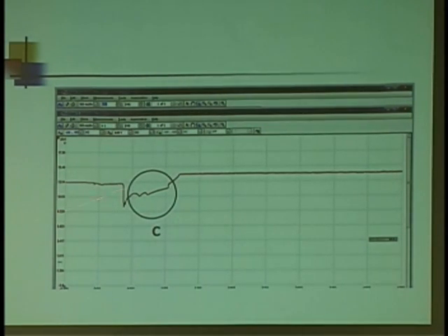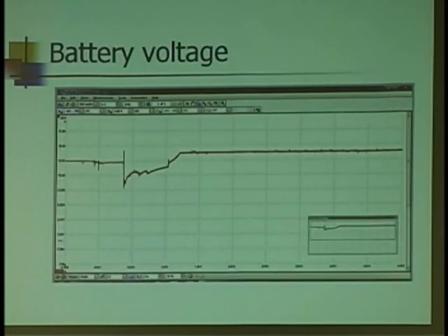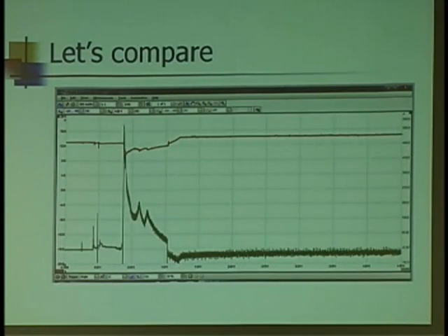Now I got these two little humps and then a slight upslope. All you're seeing there is a mirror of what you see right here. What is that? Started actually cranking. Yeah, remember the relative compression test? That's the first few pistons coming through compression. And I see that mirrored right here in the voltage.